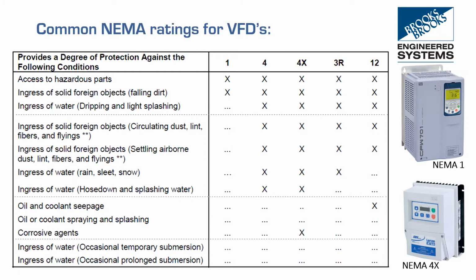Essentially, we're getting a combination of a few things, but heat seems to be the big answer. That is the predominant concern. VFDs inherently, because they're switching at such high frequencies and high power, create a lot of heat. And with the NEMA 1 drive, there are open slats and fans inside, and we can just blow that heat away. So there's no issue with having a 100 or 200 horsepower NEMA 1 VFD.